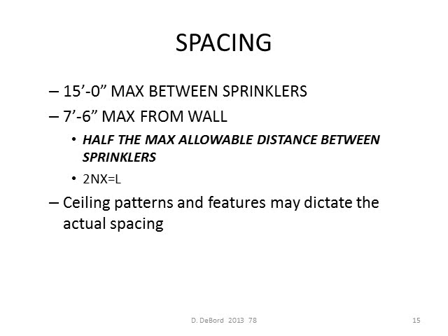And from the other side, you could be half of the maximum between the sprinklers, which is 10 feet in the other direction, so that gives you 5 feet. So each sprinkler is covering no more than 120 square feet. How does the sprinkler know what shape to go in? It doesn't. As we've looked at before, it's just spraying out. The point is we have a theoretical density that we're trying to accomplish, and that is done by following these methods.